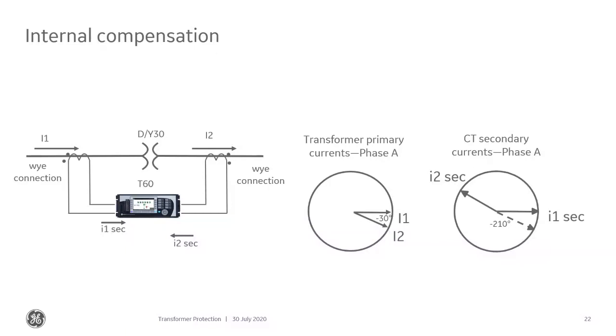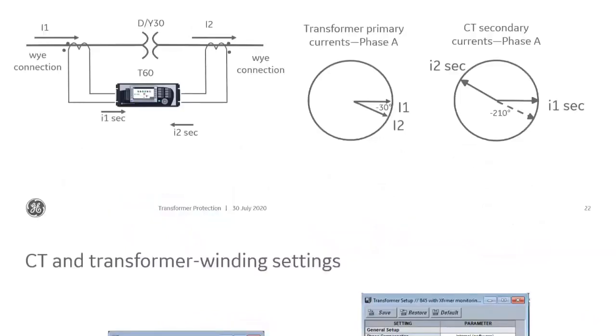Now, the way that we actually set this up, and these are settings from an 845 relay. So the 845 is the 8 series relays, the 8 family of relays that have transformer protection in it. So we need to set up the 3 windings.